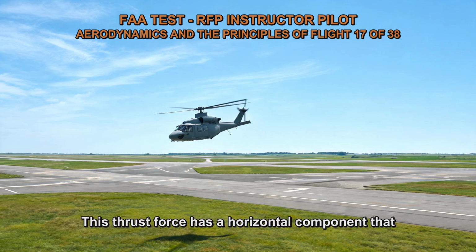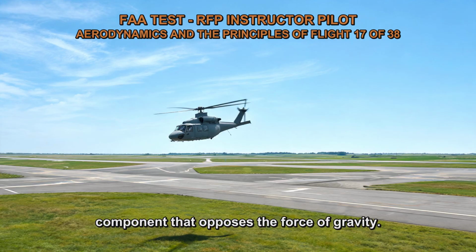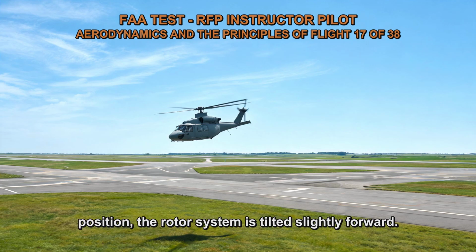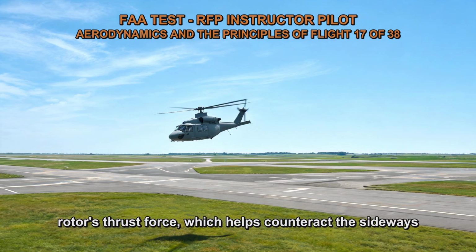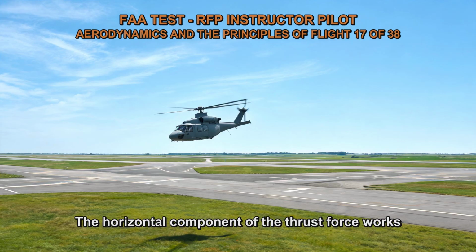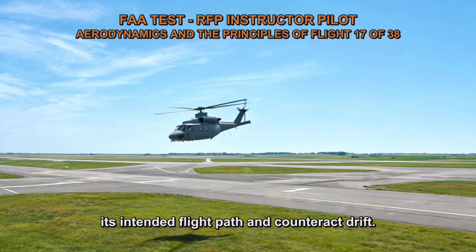This thrust force has a horizontal component that contributes to the forward movement and a vertical component that opposes the force of gravity. By rigging the mast away from the vertical position, the rotor system is tilted slightly forward. This tilt introduces a horizontal component to the rotor's thrust force, which helps counteract the sideways drift. The horizontal component of the thrust force works against the lateral forces, helping the helicopter maintain its intended flight path